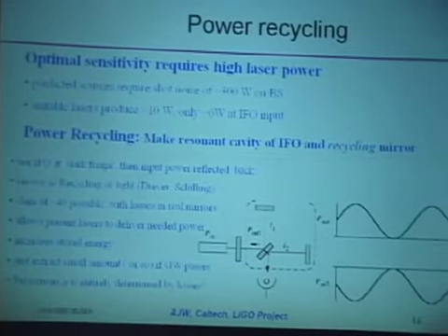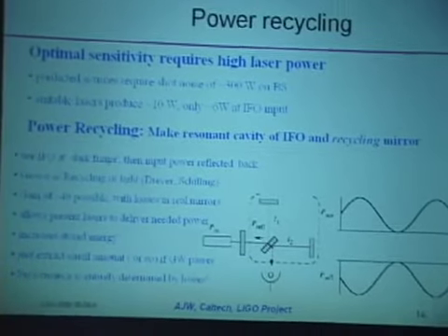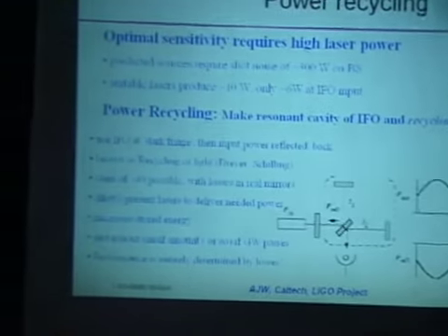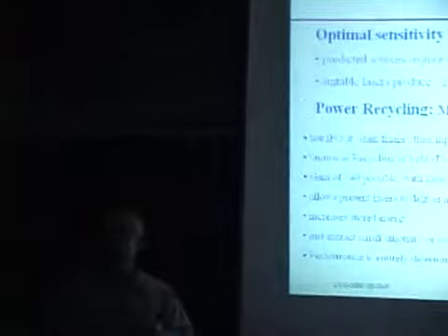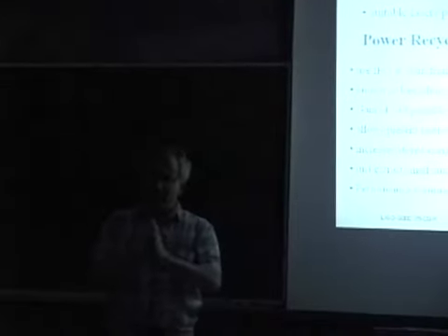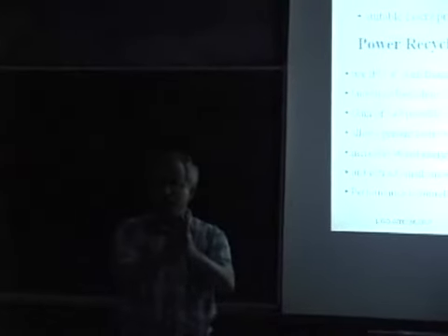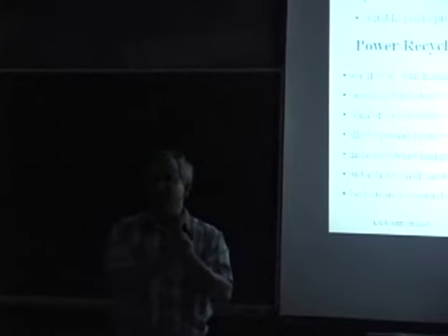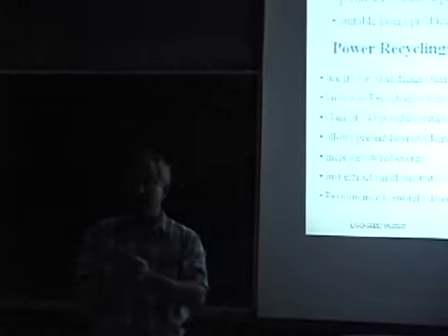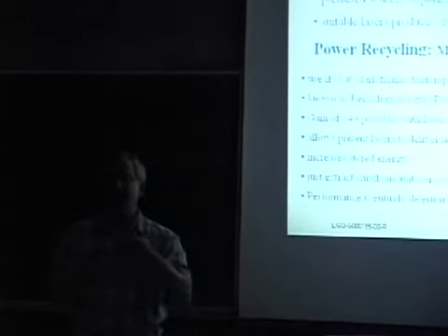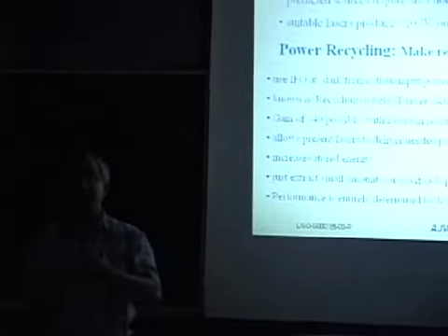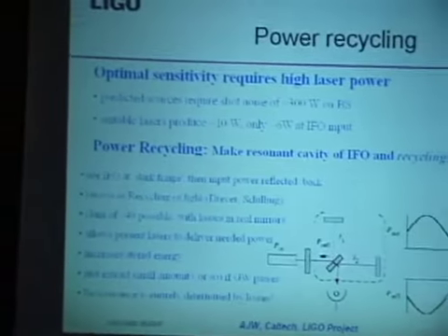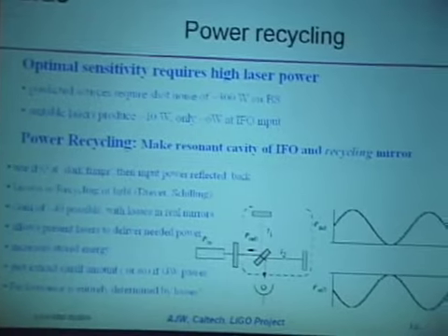And that is limited by the fact that the light that comes out is coming in discrete packets, photons, and the photons are coming in a little bit at a time. For very high frequencies, you're opening up your window for a very short time and looking how much light goes into your photodetector, and you're getting to the point where you're counting individual photons. And then statistical fluctuations, Poisson fluctuations in the number of photons limits you. And that's shot noise. The shot noise in your photodetector is white.